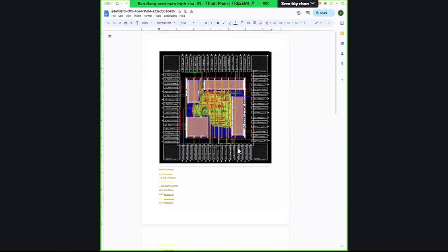So just review the macro placement and the blockages. Turn off all the standard cells and see where the rows are. If those rows are very short, you completely don't want those. Just block them out.